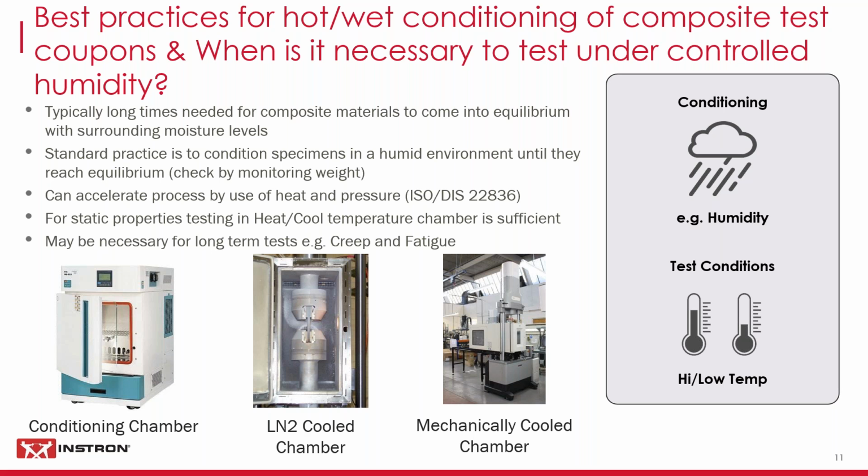On the other hand, if you are doing long-term tests, like a creep test or a fatigue test, then it may be necessary to maintain a humid environment on a constant basis. And this can be done with mechanically cooled chambers on the testing machines with humidity, and with the appropriate selection of grips, which obviously need to work reliably in the humid environment. Grips would also generally need to be heated so that there isn't an excessive amount of condensation on the grips, which will interfere with the humidity control.